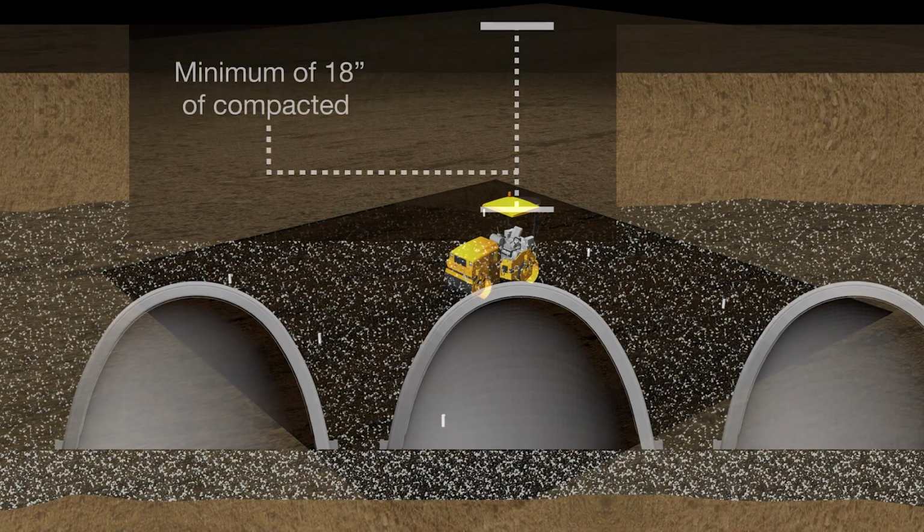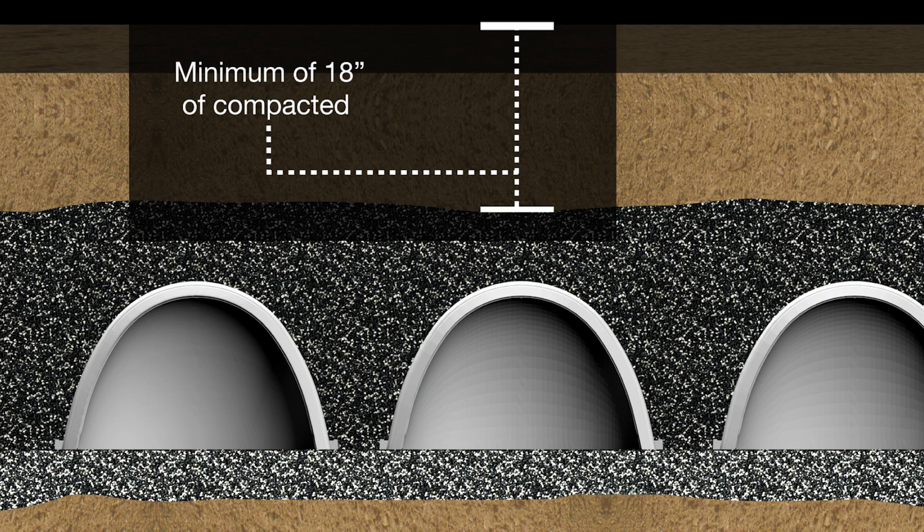The minimum cover requirement for the chamber system is designed to support a paving operation, and therefore a portion of this minimum cover would include the pavement subbase constructed to roadway standards.